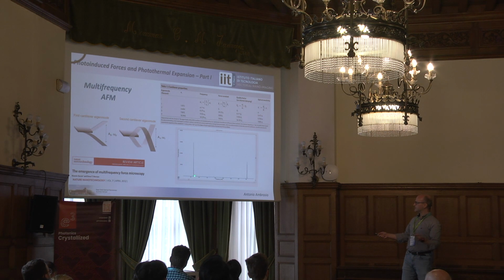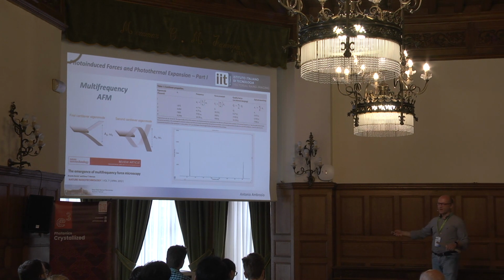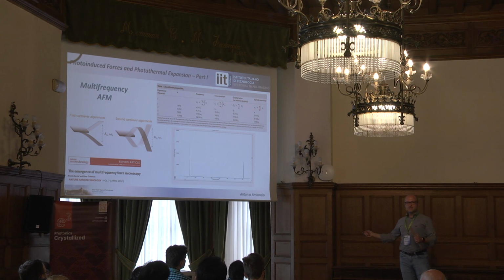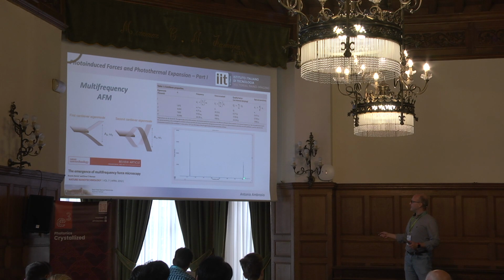If you see this is a medium soft cantilever, 75 kilohertz, that means the second mode is around 400 something kilohertz. And since, at this point, you know that we are somehow gonna use both, this is what I was telling you about the stiffness and the bandwidth of your controller, because now 75 and 400 are within 500 kilohertz.